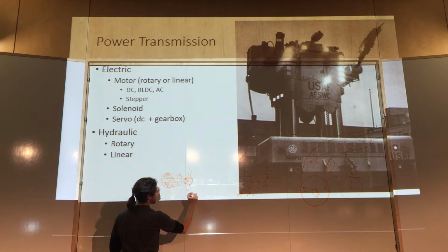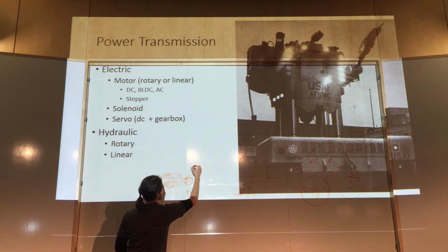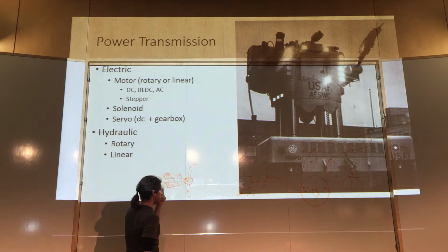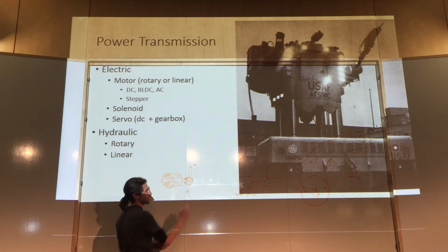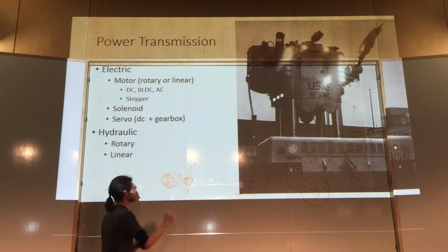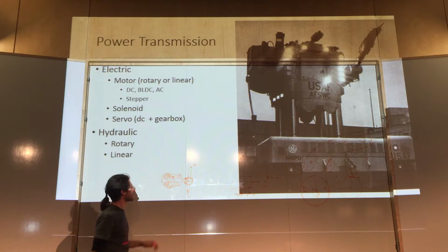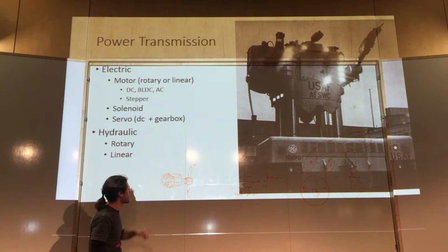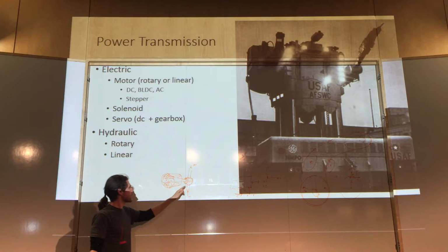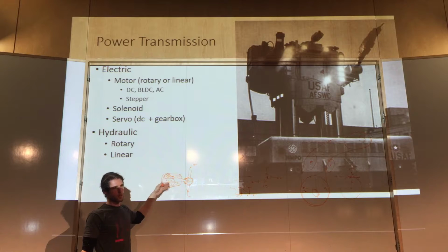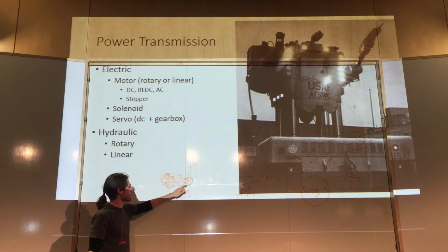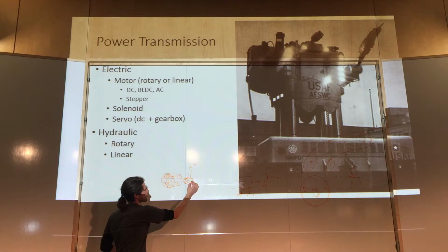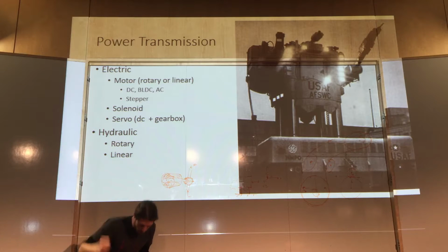There are these carbon brushes that have power going into them, called positive and negative. And it's literally just these contacts that start and stop again. That changes the direction of the magnetic field in here so that it can continuously rotate in one direction. And they're great because they're cheap, because this is just carbon and some metal and copper. And you can dump as much current as is necessary, as long as you can keep this thing cool, in order to generate torque. But every time that brush passes over this little gap, it sparks a little bit.